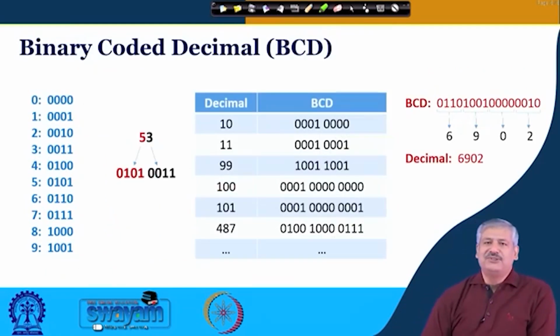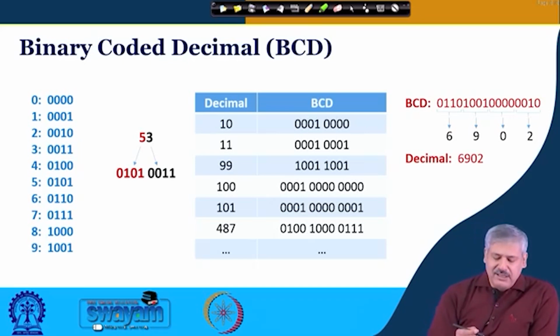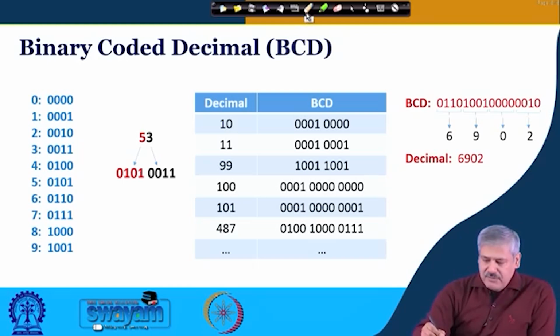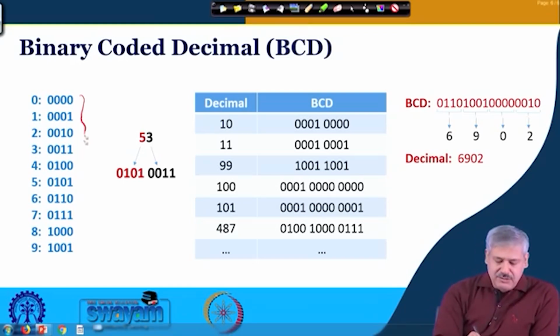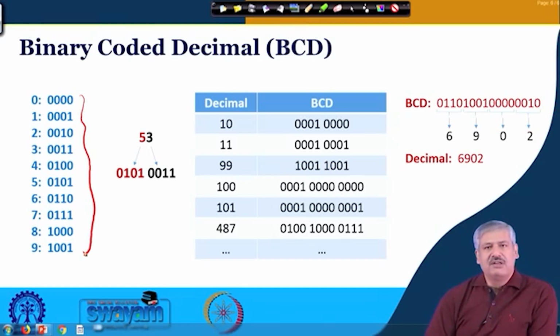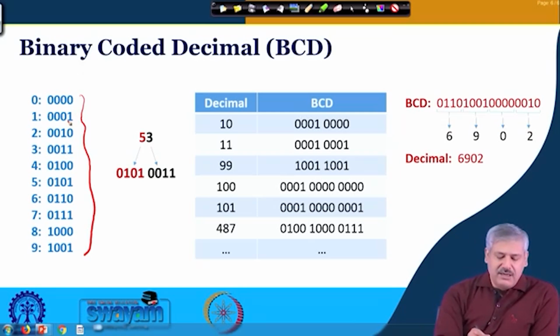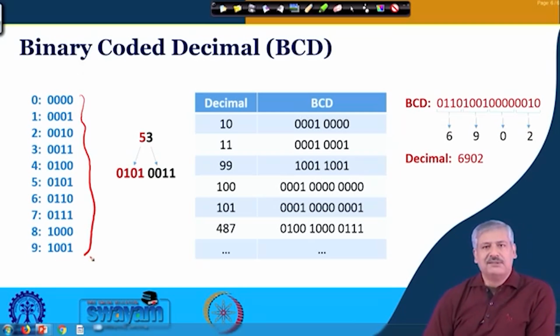Now, we will look into BCD addition and subtraction. So, before that again we look at how BCD numbers are represented. BCD numbers are binary coded decimal, we have seen BCD decoding and other things before. We are already familiar that BCD digits are from 0 to 9. So, this is the decimal representation, you have got digits from 0 to 9, and the corresponding binary codes are 0000 to 1001. So, in BCD coding any number more than that is not valid.